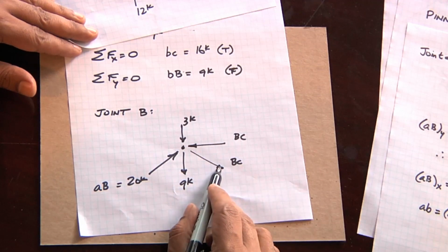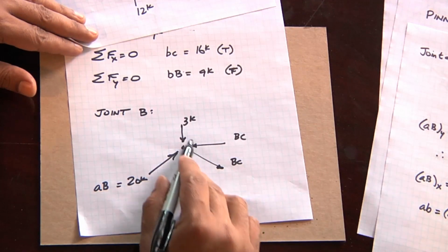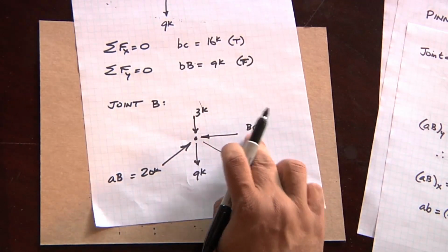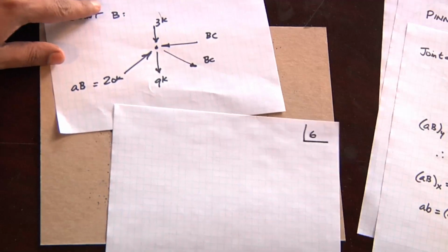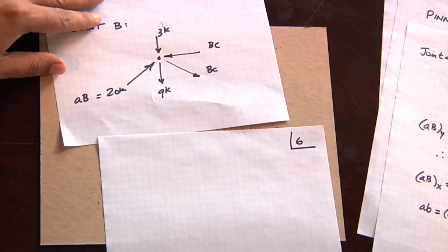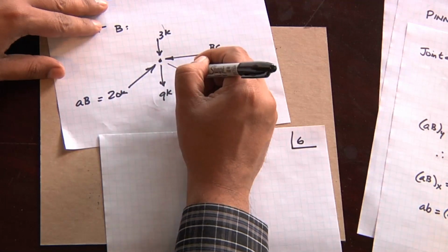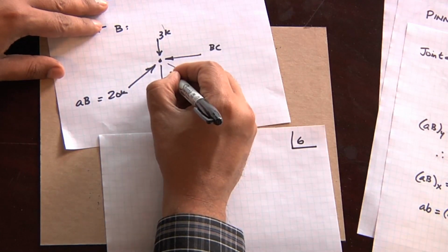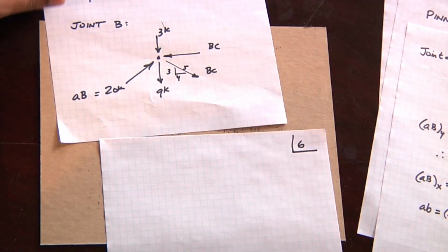The other way you can also tell is you can sum the forces in the y direction. That's a fairly simple way to solve this because BC cancels out. The horizontal chord force cancels out. Let's take a look at that calculation. So this is sheet number 6. What is the slope diagram here? Well, same slope diagram as we had before. It's going to be a 3-4-5 triangle.